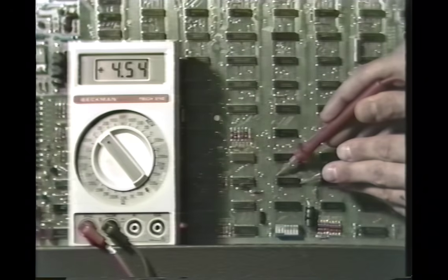When the bad filter capacitor causes excessive ripple in the power supply, one of the symptoms is a lower than normal reading at the output when you check the DC voltage. Well, standing alone, the DC measurement can point to either of two possible failures. Either the DC output of the regulator has indeed dropped due to a regulator failure, which would be the obvious first guess, or the low DC reading is being caused by excessive ripple in the power supply as a result of the defective filter capacitor. When you make the DC measurement, you have no way of knowing which of the two possible causes is creating the low reading that you see.